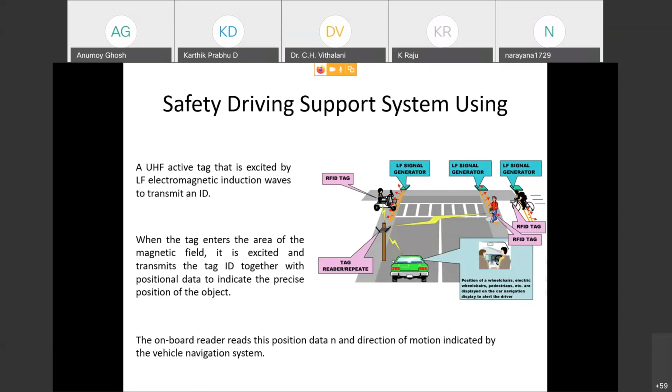What I want to say is that, lastly, vehicle management using RFID is a very open field of research. Very open field. There are numerous challenges. Some of the challenges that I can tell you right now are designing exactly circularly polarized antennas for readers or omnidirectional antennas for tags, and matching the antenna network with the semiconductor network. Good matching, because research is still going on into how to achieve perfect matching between a tag and a semiconductor chip, that too in the gigahertz range, because a vehicular RFID system will be working in the gigahertz range.